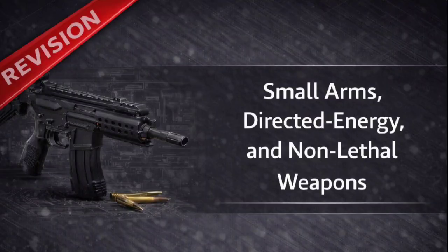Okay, let's transition now to the third and a highly specialized system, gas operation. This is the method we see in most modern assault rifles. How does it harvest energy compared to the other two? Gas operation is unique because it actively taps the high-pressure propellant gas. It taps it directly from a port that's drilled into the barrel. So it's bleeding off gas from inside the barrel. Exactly. As the bullet passes this port, a portion of the gas bleeds off into a gas cylinder, and it drives a piston. That piston then strikes an operating rod, which performs the mechanical actions to unlock and cycle the breech block.